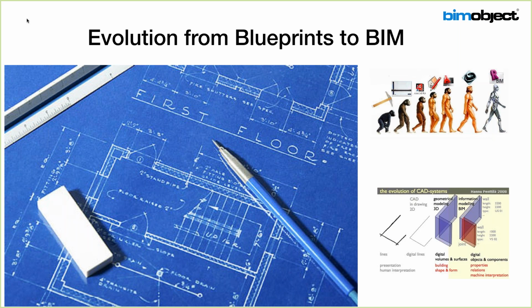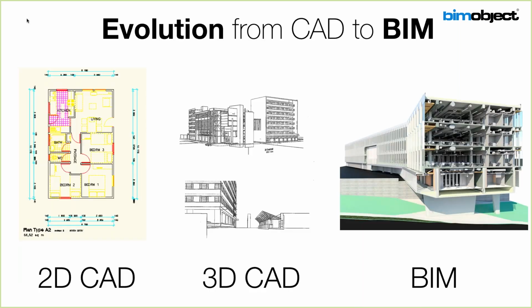To move into now where we're into building information modeling, which is that same geometry, but it has values, it has weights, it has, in the case of a valve, certain flows. In the case of a window, it might have a U value, and in the case of a door or wallboard, it may have an STC rating. These are all critically important to the overall products.